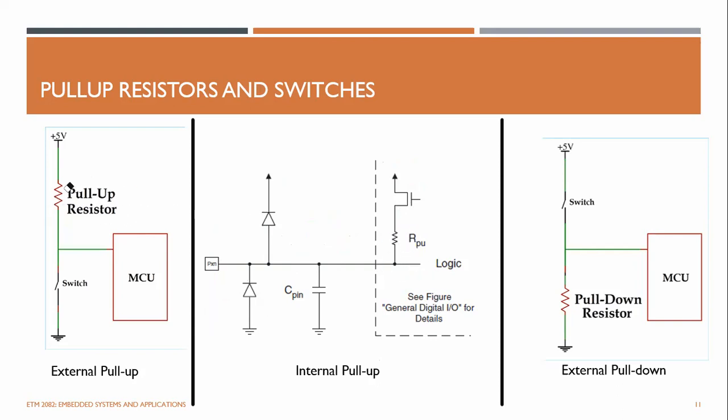You don't need to pay for external resistors, and you don't need to deal with the PCB layout because it is already available. And this pull-up resistor is voltage independent. Like if it is around 20 kilo ohm, no matter whether you use 4 volt or 5.5 volt, the resistance won't change. It is not the resistor that you see from the market, right? Like this kind of resistors you have seen from the market, or this kind of surface mount.